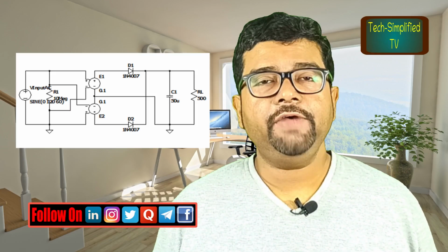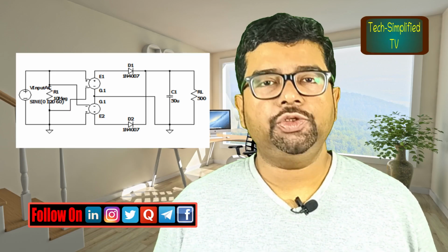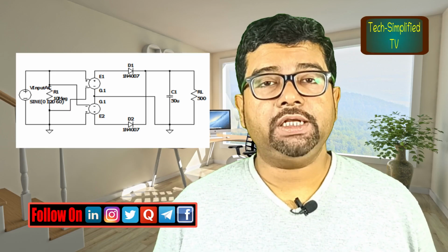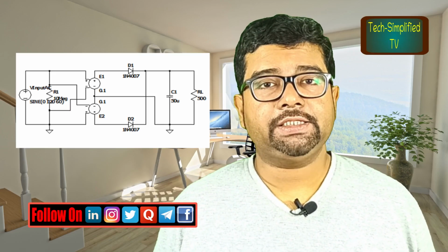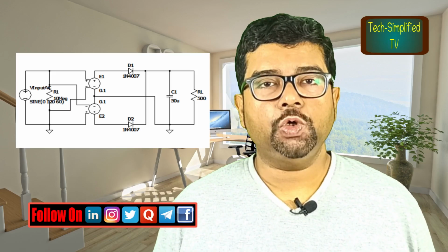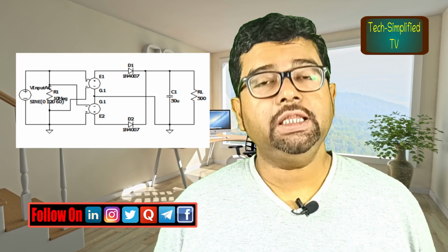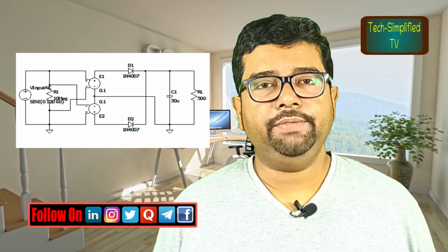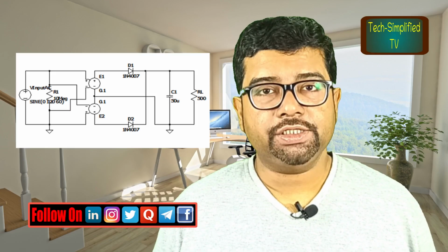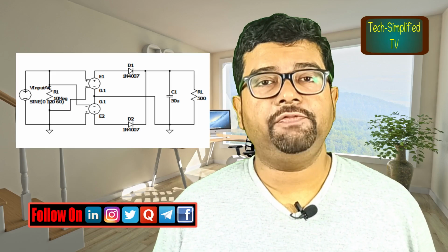1N4007 diodes. We face a challenge in this since we do not have a transformer in LTSpice, and we overcome it by using an equivalent circuit using two VCVS, that is voltage controlled voltage sources, which we have learned in the theoretical episodes already. We will use a sine wave input and a transient analysis to explore the full wave rectifier circuit.